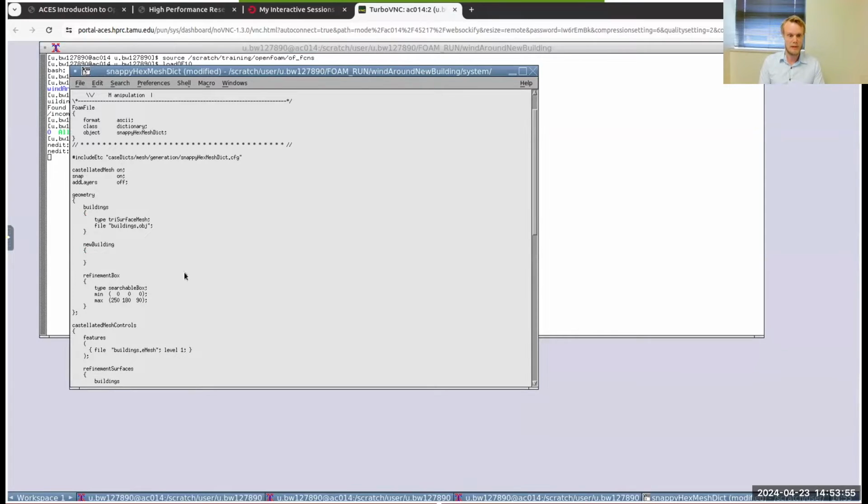And then OpenFOAM has a bunch of different ways to define geometry. One is, of course, to use a CAD file, but OpenFOAM has some built-in shapes, one of which is a cylinder. So we're just going to make a cylindrical tower for now. We type searchable cylinder, type semicolon. And a searchable cylinder in OpenFOAM is defined by 2 points and a radius. So we type 0.1. Let's say we put it at x equals 150, y equals 30, and it starts,